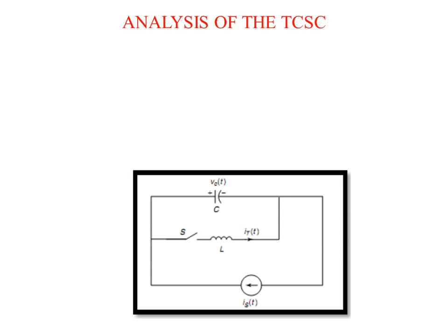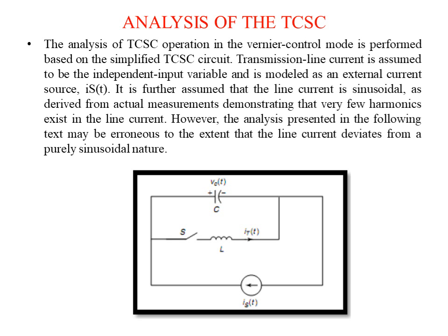So this is the equivalent diagram of figure number one. That is, we have a capacitor in series and the parallel inductive branch over here. The analysis of TCSC operation in Vernier control mode is performed based on a simplified TCSC circuit.